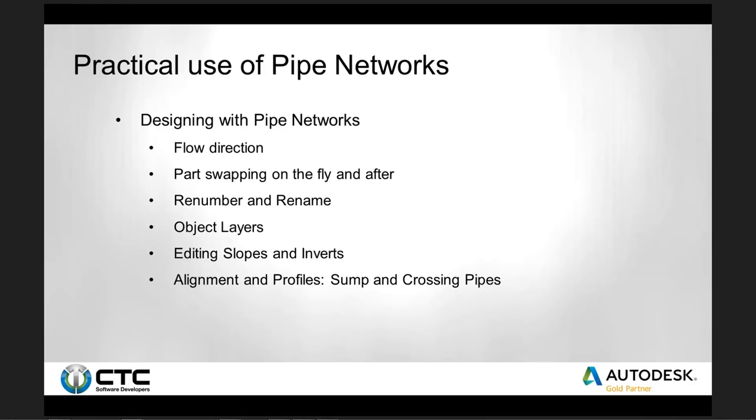We'll talk about parts swapping. You dropped in a storm manhole, you wanted a catch basin instead. How do you swap that, and what's implied with that? It's a very powerful tool, and it should be used in any kind of modifications in your pipe network that you're creating. So we'll talk some about that.